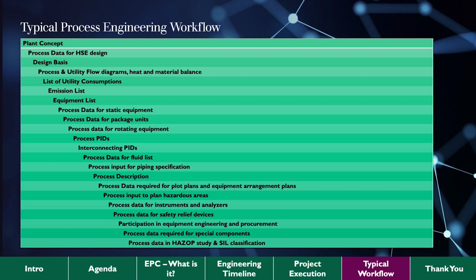But once you have completely clarified that, you need to go for the design basis, and that's basically the Bible of the project. It's a document that specifies, in a quantitative manner, everything that came out of the meeting that the EPC firm and the customer have agreed upon.